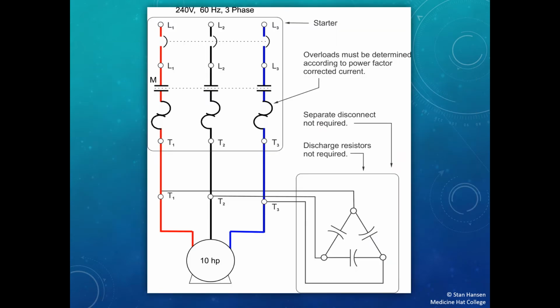When we are required to install capacitors to offset a motor load, there are 3 general locations that capacitors can be placed, and these are all covered within Rule 26.218. The first example is to place the capacitor on the load side of the motor starter.